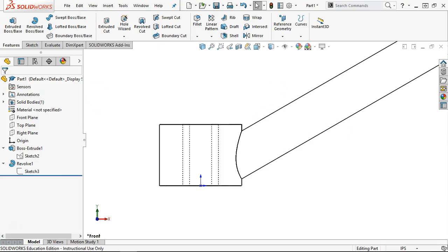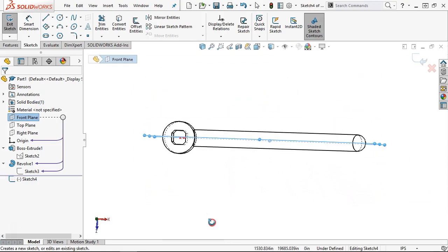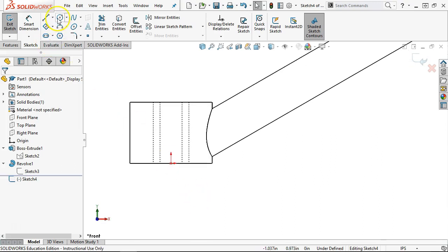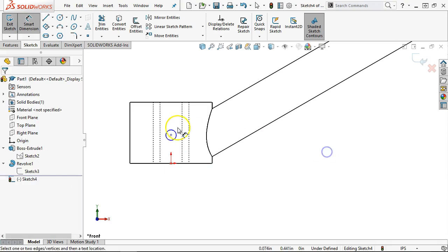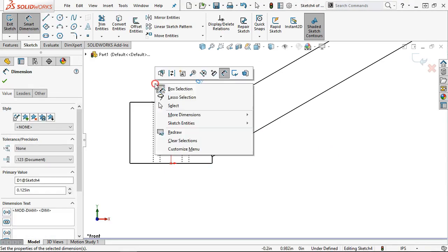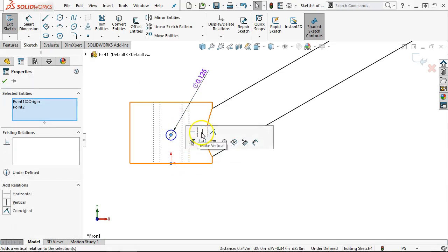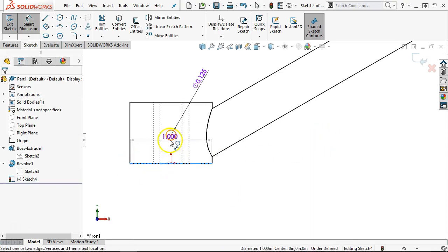So the 1/8 inch dowel pin hole will just go into the front plane, and keep in mind that the front plane bisects the part. All right, so when I draw this on the front plane, we have an 1/8 inch hole, and we had the discussion of when to use the hole wizard and when to just go ahead and make it a cut extrude.